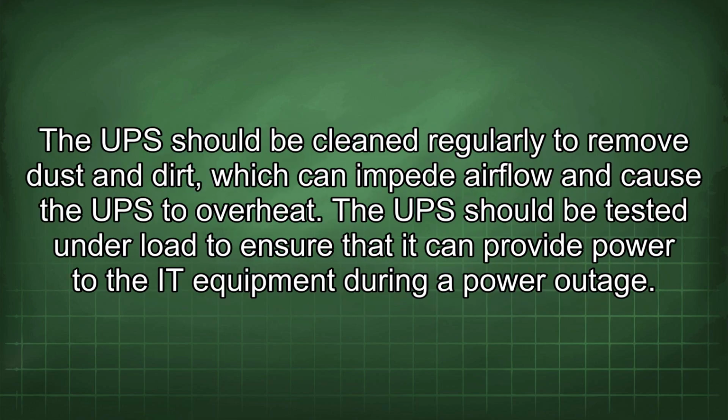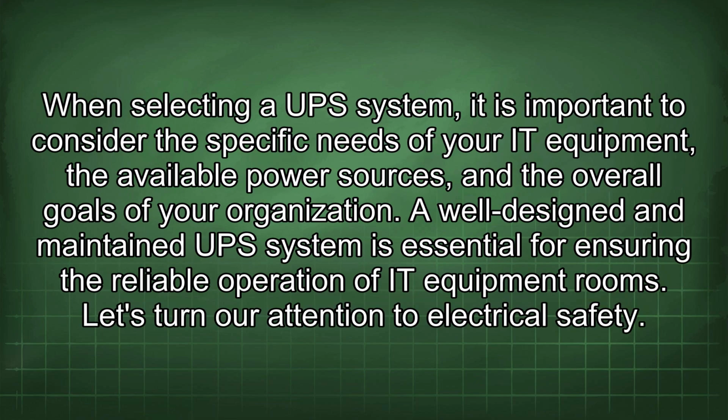The UPS should be cleaned regularly to remove dust and dirt, which can impede airflow and cause the UPS to overheat. The UPS should be tested under load to ensure that it can provide power to the IT equipment during a power outage. When selecting a UPS system, it is important to consider the specific needs of your IT equipment, the available power sources, and the overall goals of your organization. A well-designed and maintained UPS system is essential for ensuring the reliable operation of IT equipment rooms.